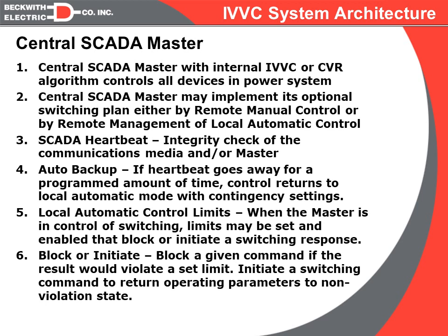The other reason we want to have some smarts in our local controls is to actually supervise the IVVC software. So we want to set limits in each individual control. For instance, I don't want the voltage to ever get above 126. And if the SCADA Master sends a command to me, and me acting on that command is going to make the voltage go above that level, I need to disregard that command first of all, and then secondly, I need to inform the SCADA Master that I did not act on that command because it would have driven me above the high voltage limit. So we want to be able to block SCADA commands if they're going to drive us outside of predetermined limits.